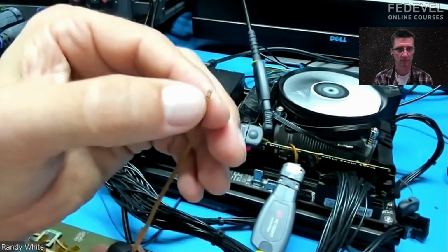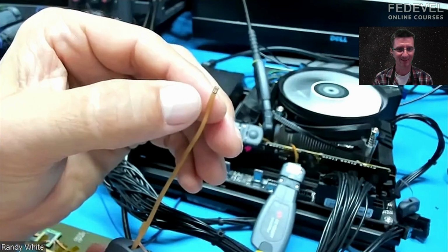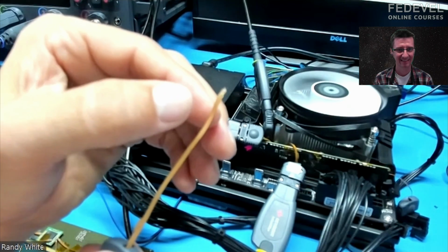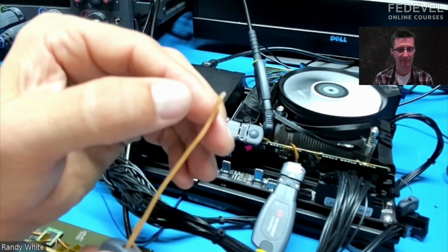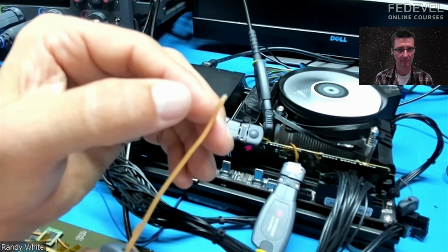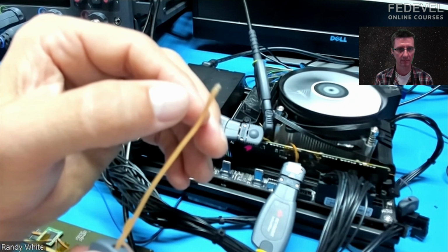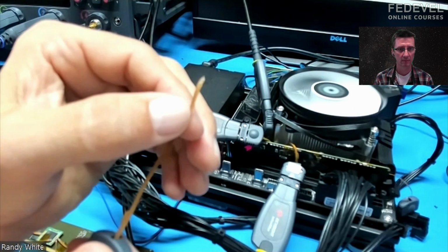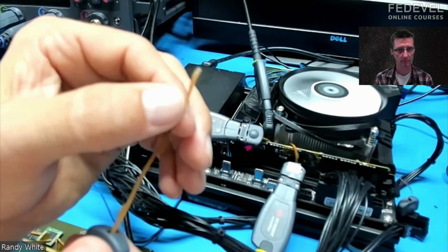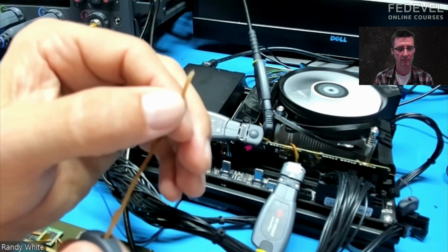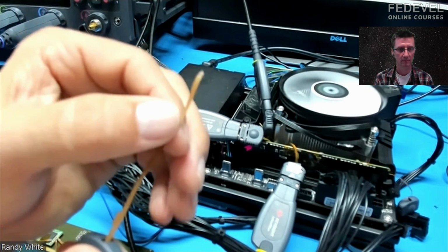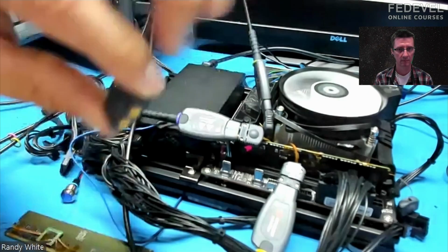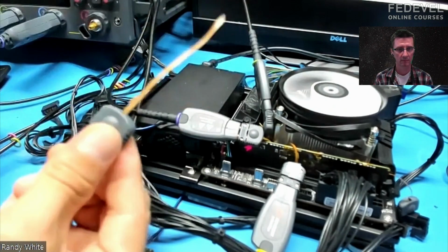And on the very front, now it's focused. Yeah, there's 102. It's not 0402 resistor component size, but it's the next size below: 0201 surface mount resistors, the 110 ohms that are used for dampening reflections. When we solder on, there's a discontinuity. So that's our probe head right there.